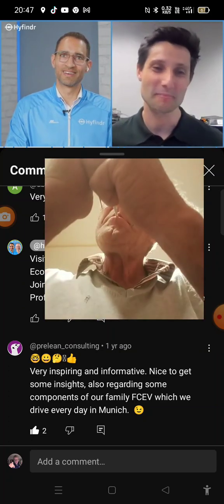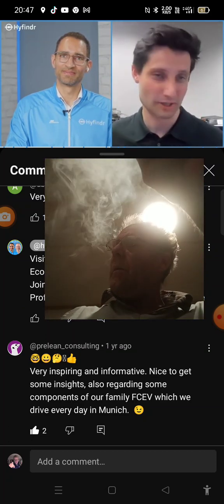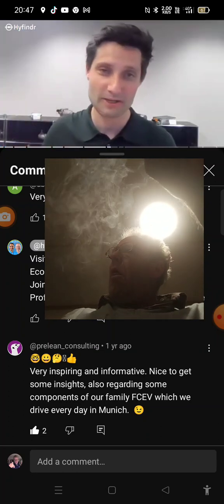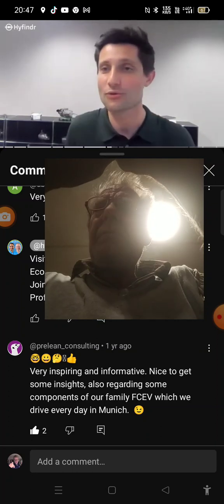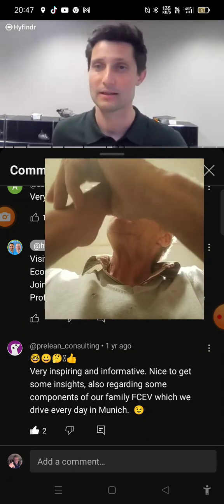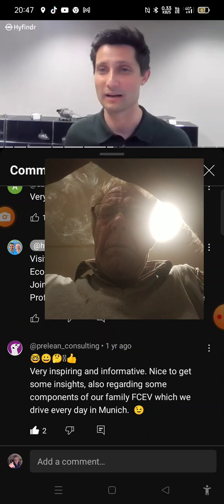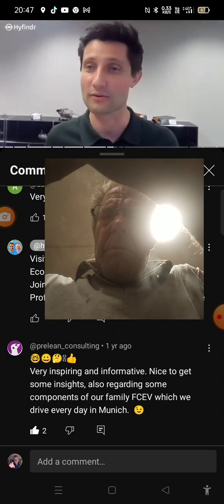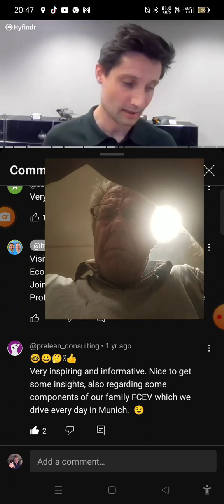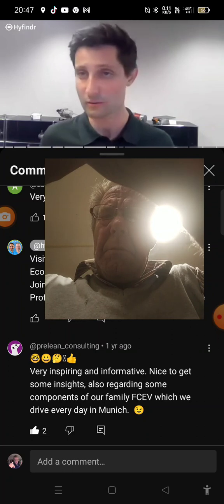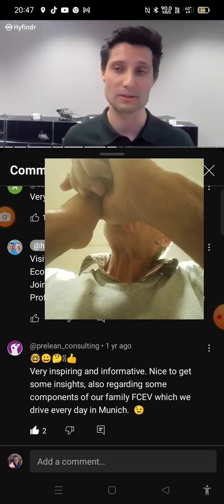So maybe to give you a couple of values here, which might be interesting for the viewer as well. We range between rotational speeds of around 120 kilo RPM, so 120,000 RPM, for the larger compressor, up to 300,000 RPM for the smaller systems. Usually, which means when we convert that into velocities, we're talking about 300 to 400 meters a second. Wow. So generally speaking, the sound barrier is something we try to avoid because supersonic operation always results in shocks.